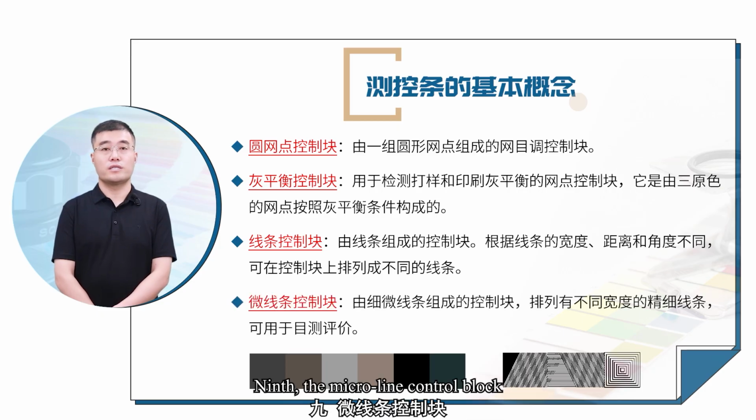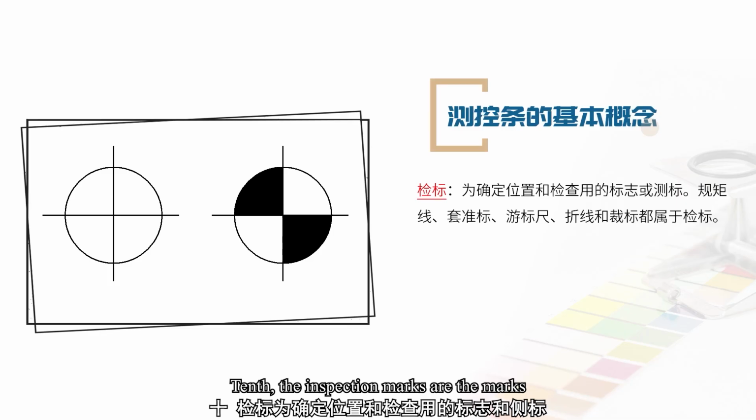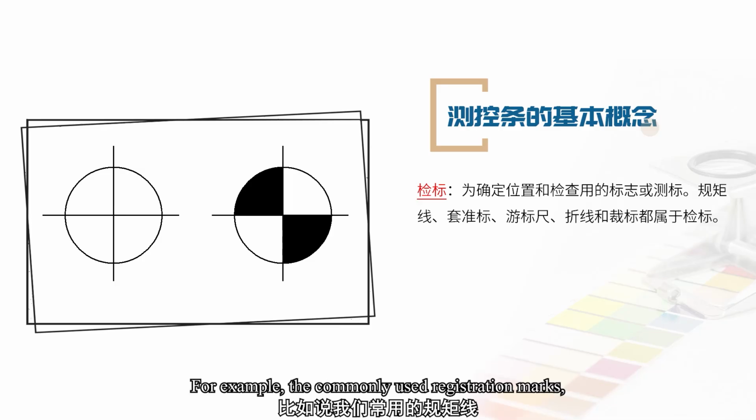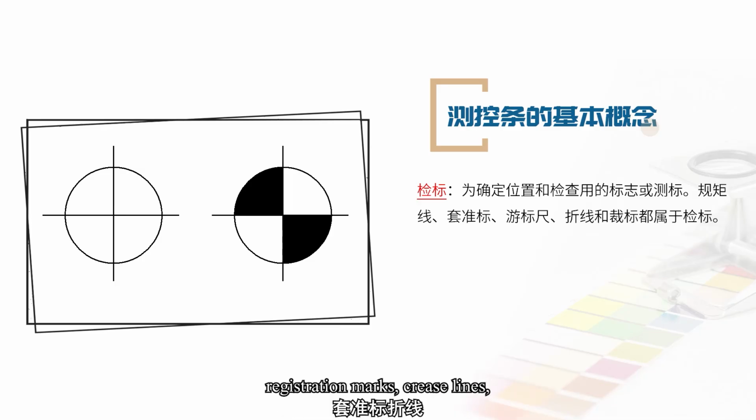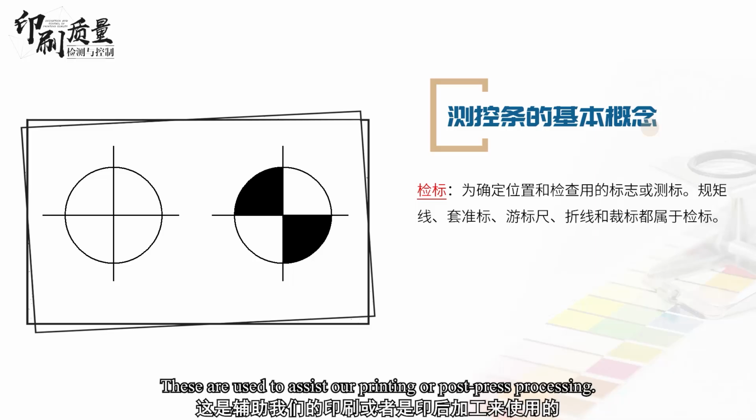Ninth, the micro line control block is a control block composed of fine lines. It has different widths in its arrangement. It is a fine line and can be used for visual evaluation. 10th, the inspection marks are the marks and side marks used for determining the position and inspection. For example, the commonly used registration marks, crease lines, and cutting marks all belong to the inspection marks. These are used to assist our printing or post-press processing.